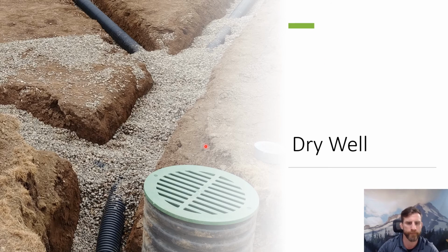All right, here are some pictures of dry wells that we put in. Again, this is a drainage project we installed at the Lewis Brown farm. You have a series of drain tiles here and stone going over top of them. We'll eventually put some sand over this as well. And these tie into this dry well here, which also is going to have a perforated cover over the top of it, which allows more surface water to infiltrate down into it.